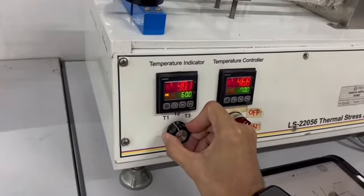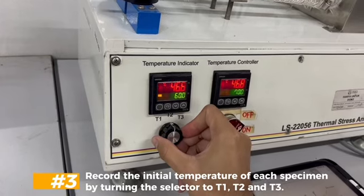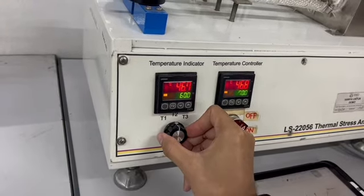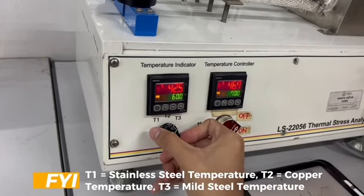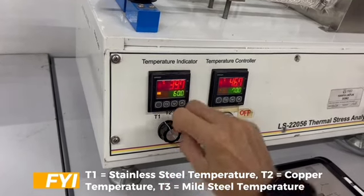After that, we need to record the initial temperature of each specimen by turning the selector to T1, T2, and T3. For your information, T1 is for stainless steel temperature, T2 is for copper temperature, and then the last one is T3 for the mild steel temperature.